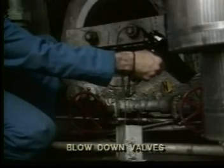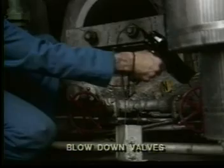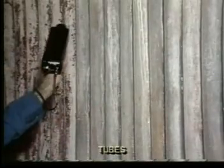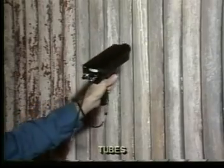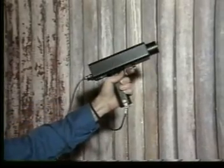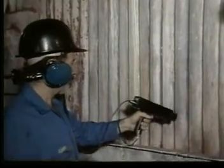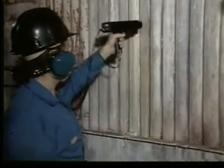Blowdown valves are checked by using the contact probe on the downstream side. There should be no flow. When testing tubes with the system pressurized, use the scanning module. If there is steam in the tubes, it will be necessary to scan at a distance. Note the area with the loudest sounds. Adjust the sensitivity to pinpoint the leaking tube.